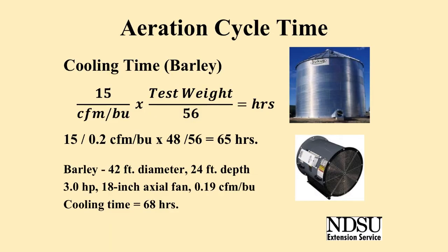Aeration cooling time can be estimated by dividing the number 15 by the airflow rate in CFM per bushel and adjusting for test weight. For example, an aeration airflow rate of 0.2 CFM per bushel will cool a bin of barley in about 65 hours.